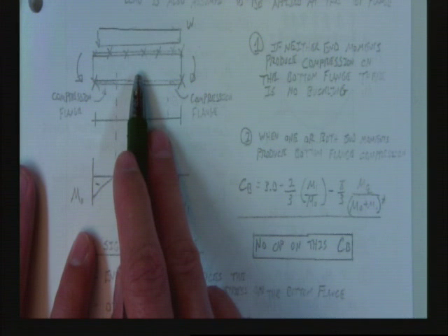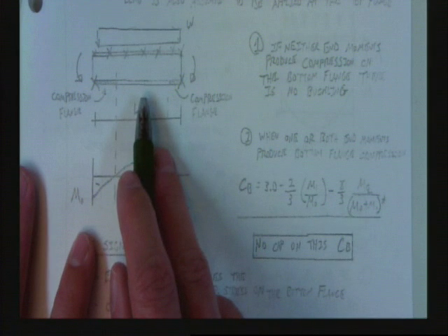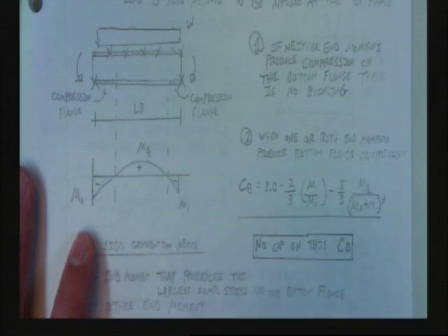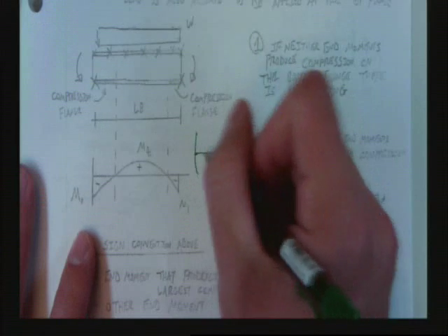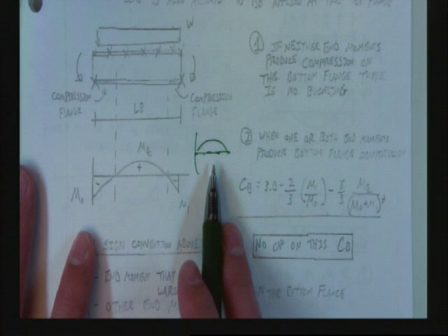Not whenever the moment is distributed like that, even if the moment's up. I mean, we're talking about a complicated moment diagram. But let's say I change the moment diagram so it looks like this. Are those effective braces? Then it comes down to how deep the beam is, remember? I said if the beam was deep, then those are not effective braces. You with me?